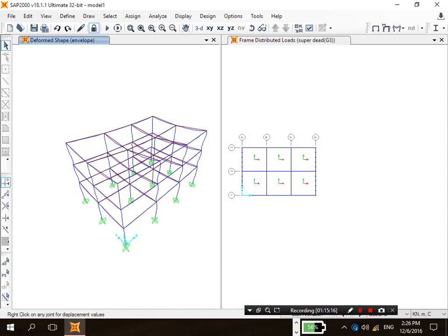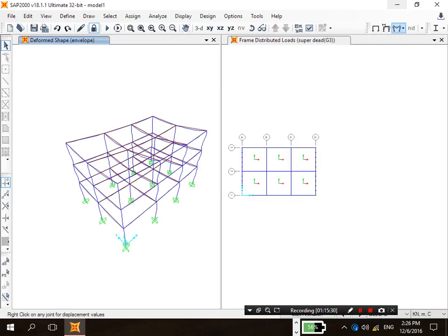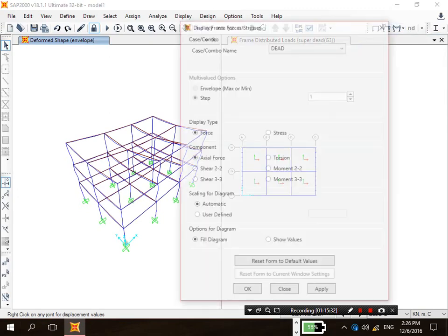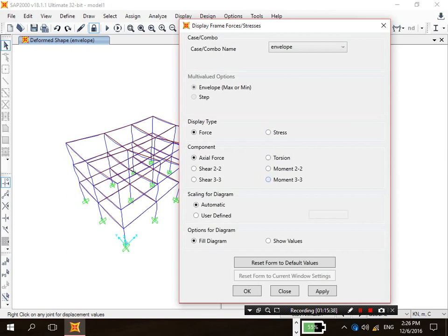However, you might have different, like 7, 8 ULS cases. And in this icon, you can see the results, the numbers, the shear, the moment, the axial load, everything. According to also envelope and moment M33, which is the in-plane moment, which is usually the one we are interested in.